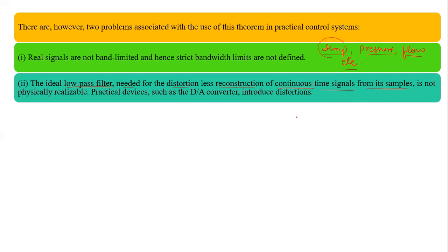Because when you have sampled the signal, you have lost certain information. Now you have processed that signal through the computer, which will give you some digital output, but you will not understand that digital output, you will only understand the analog output. So when you convert that digital into analog by using a D to A converter, you need to reconstruct the signal. The perfect reconstruction is only possible when we follow the sampling theorem.